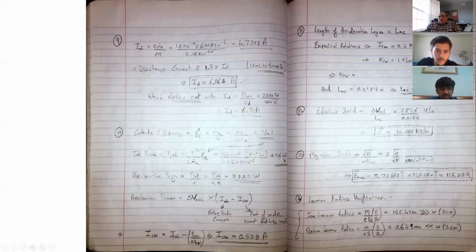And then the acceleration power is, again, there's an in-depth concept that goes into this. Why is it jet power divided by gamma? Gamma is 0.9, a factor that comes from the fact that you need to take into account xenon plus as well as xenon 2 plus. That's the factor gamma, which I haven't elaborated upon. But we are concerned with the net acceleration power, which is about 1.18 kilowatts.